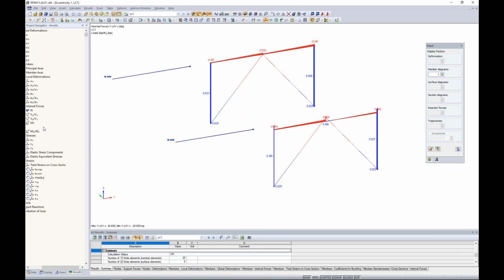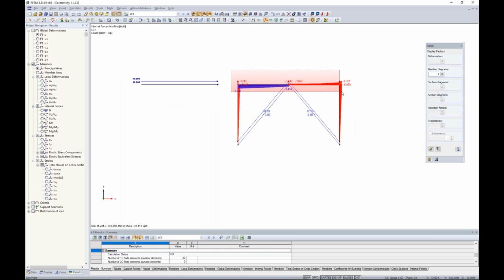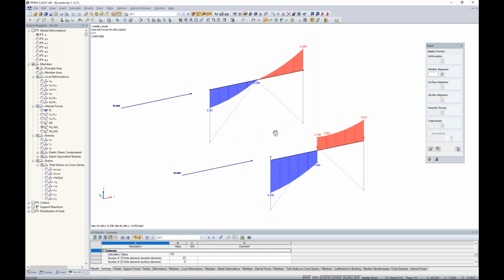But taking a look at the bending moment, the strong axis bending moment, let me create a visibility for just these two upper beams here. Well, you'll notice the drastic difference with the strong axis bending. In my first example, we transition here from a positive moment, 0 moment at the midspan, into a negative moment. Quite a different story when we've taken into consideration that eccentricity.